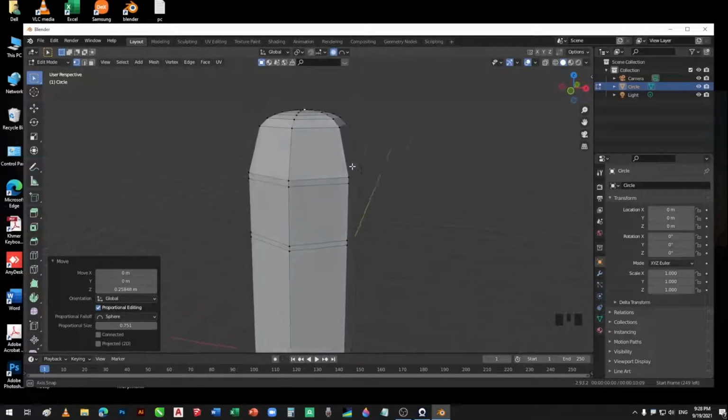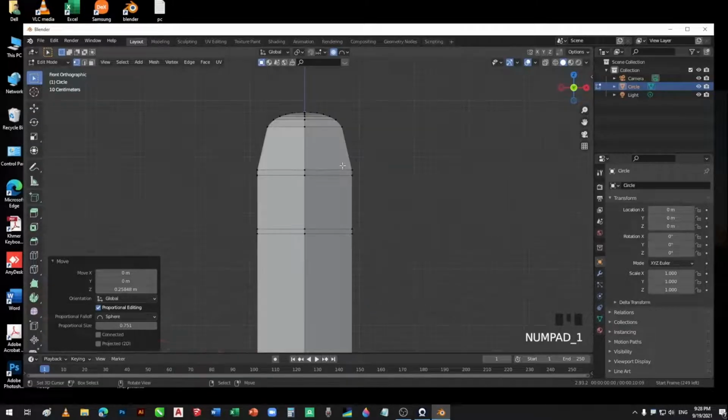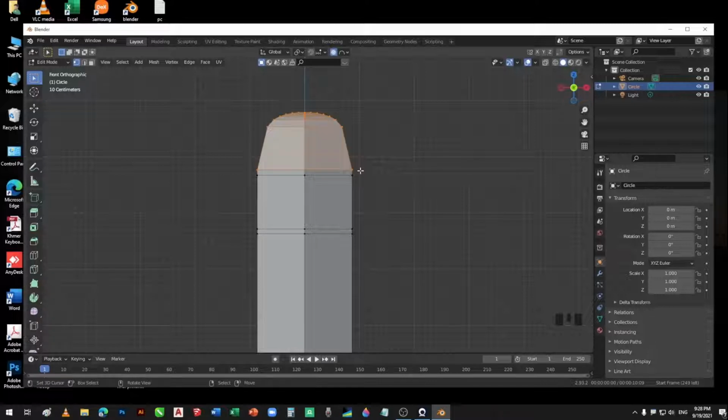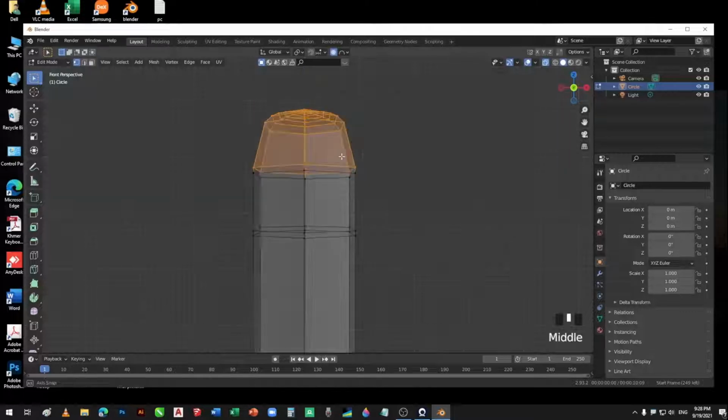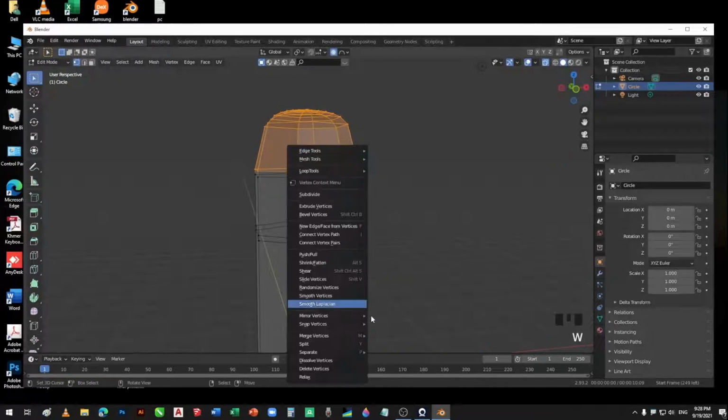In order to modify the color, it is called material, we should separate each part. In edit mode, click and drag the mouse to select the top part. If some part is not selected because the 3D object behind the part is hidden, in this case press Shift+Z or Alt+C to view wireframe mode. It looks like an X-ray body.